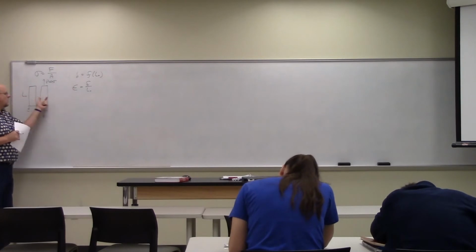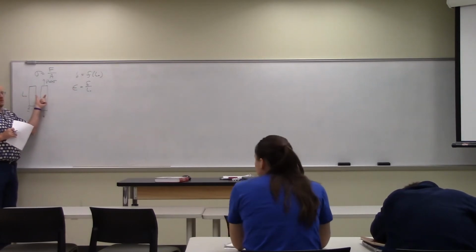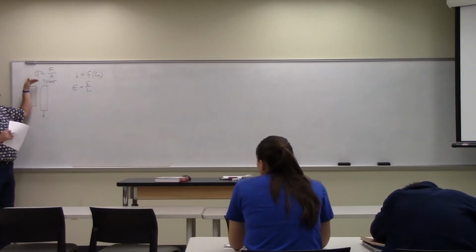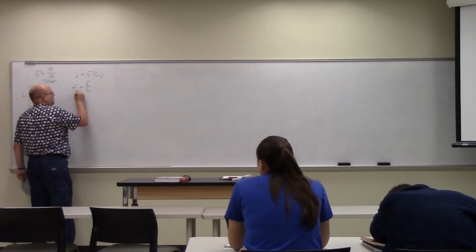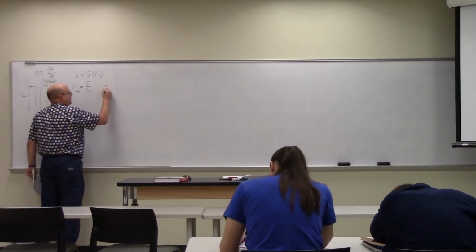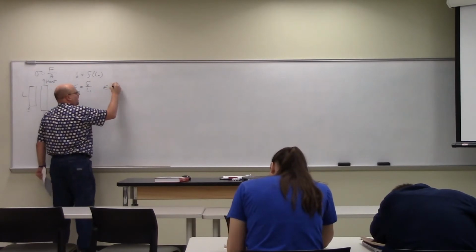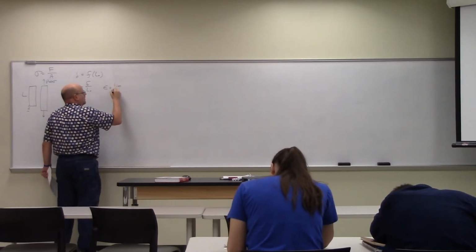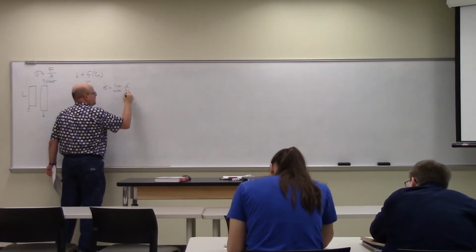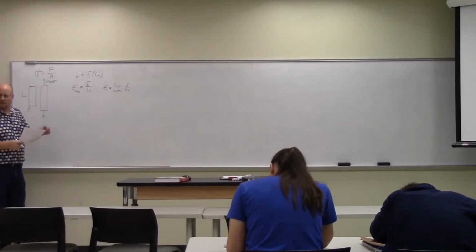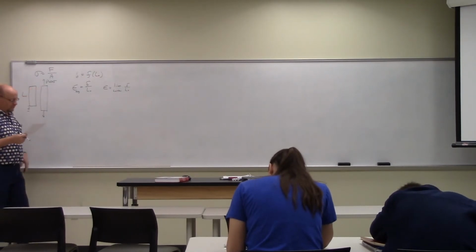Just as before, if I doubled the area and doubled the force, I would have the same stress. Okay. And that represents then the average strain. The instantaneous strain or the local strain is defined as the limit as L naught goes to 0 of delta over L naught. Right, the limit for some gauge length, it gets very small.